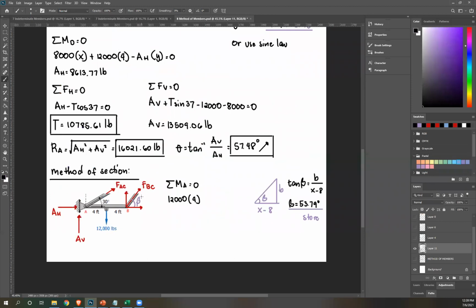So again, now we have your angle, vertical component, that's FBC sine theta. So rotate the vertical component about A, that's counterclockwise. So negative FBC sine theta, right? There's no other force. Perpendicular distance, this is the perpendicular distance, which is equal to 8 times 8.